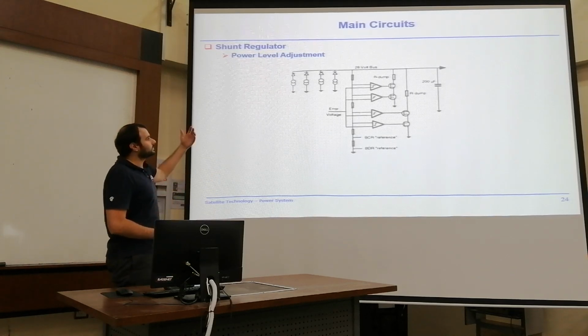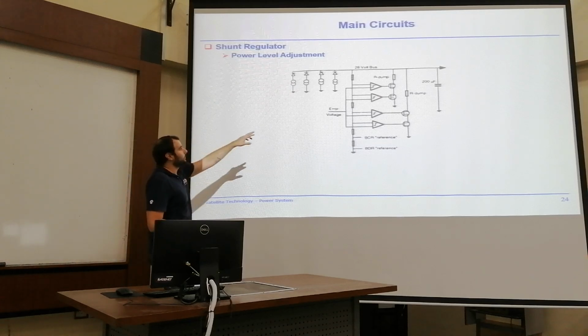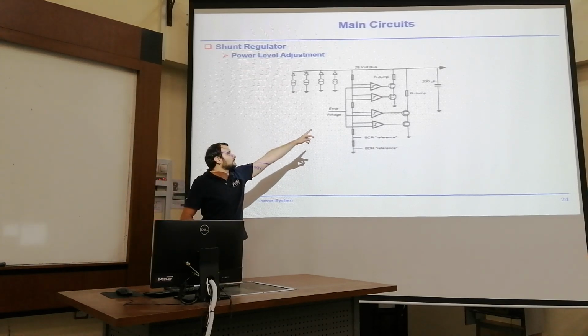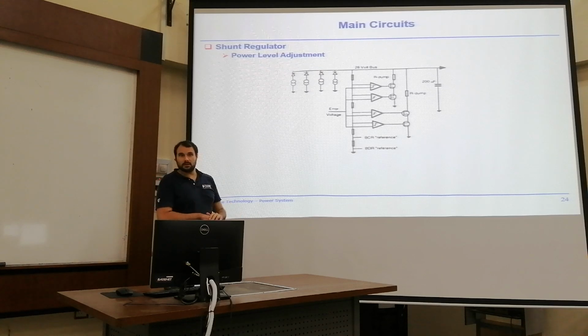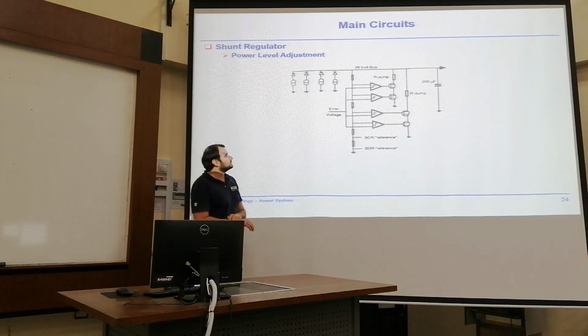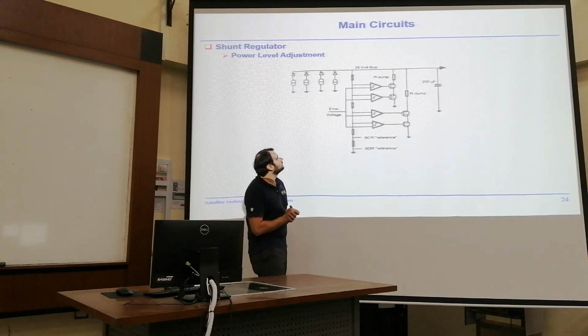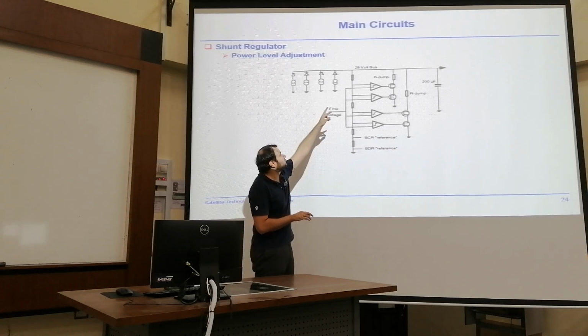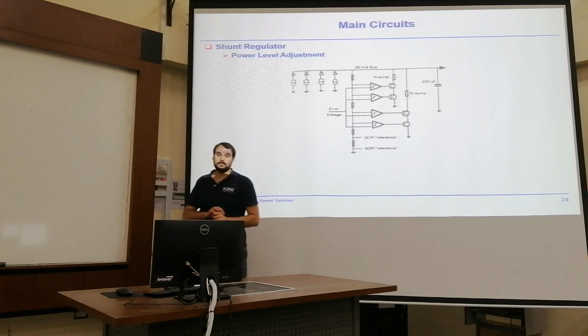And if you are above this reference voltage, your negative switches, your MOSFETs there, they are closed, they don't conduct, and so there's no connection from your voltage bus over the shunt to the ground.